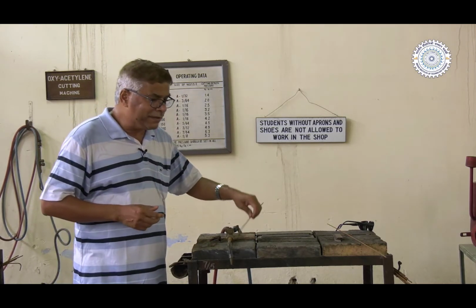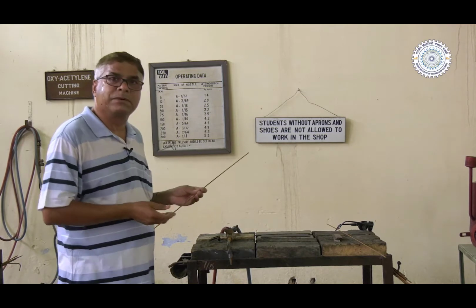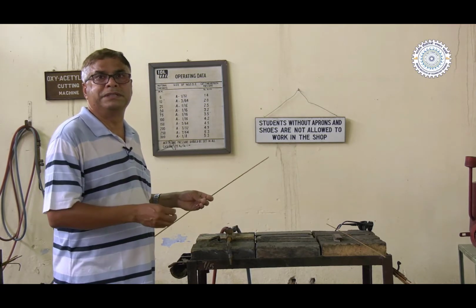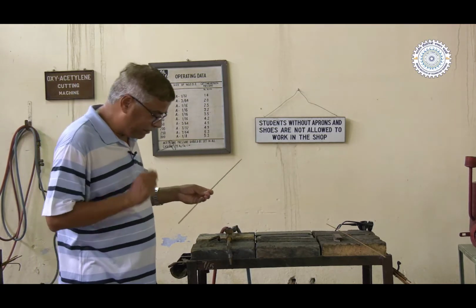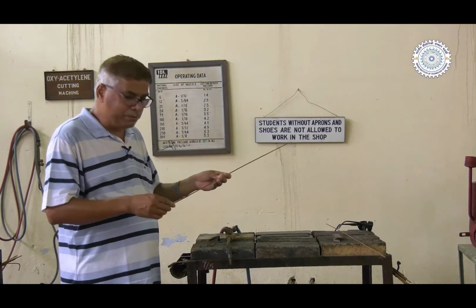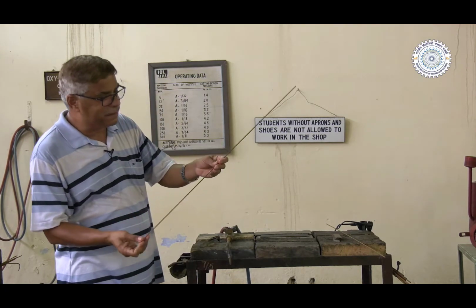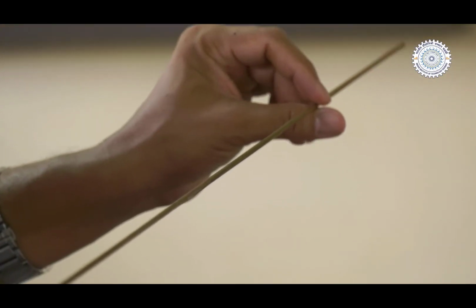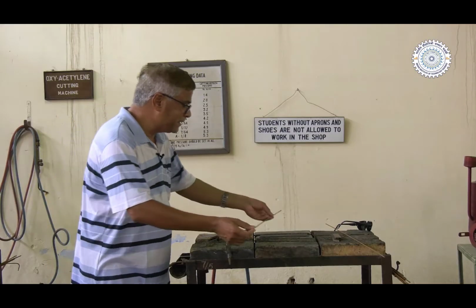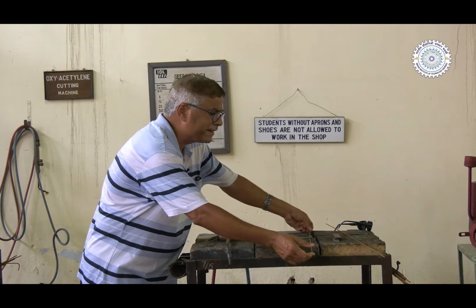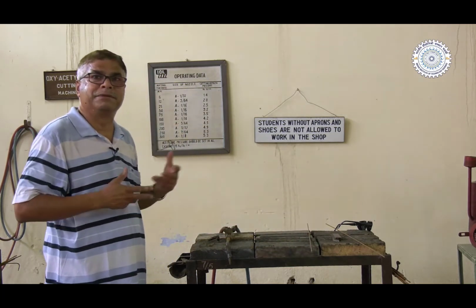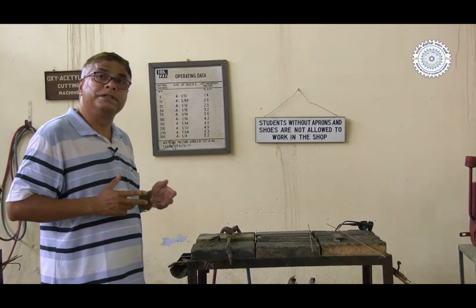Most invariably, gas welding can be autogenous or it can be done with the help of filler. If filler is to be used, then the filler is just like simple steel which is copper coated in order to avoid rusting, and fillers of different sizes and diameters can be used as per the need of the joining.